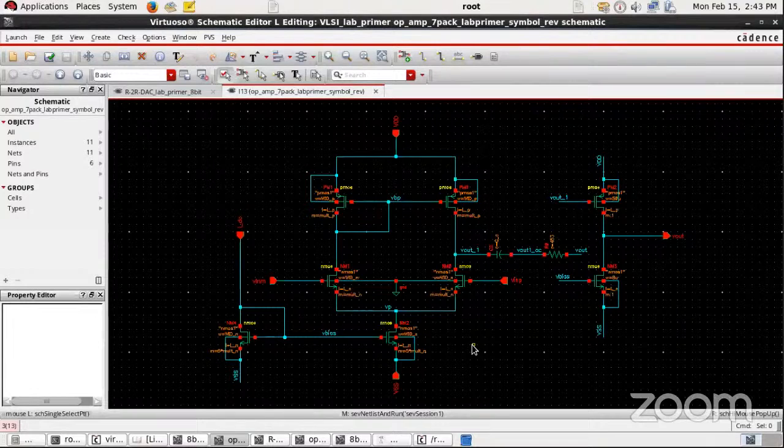So we have connected two common source amplifiers back to back, where the NMOS pair is a differential stage. In case the PMOS pair is the differential stage, then you can use the circuit the other way.